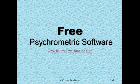Yeah, I would have to actually use the software to try to find an answer to his question. But every computer room I've dealt with, we've always used relative humidity as our determining factor. And dew point is a function of relative humidity and dry bulb temperature. And with the software, he can very quickly figure out that at a certain temperature, would you say 70-some degrees? 74.